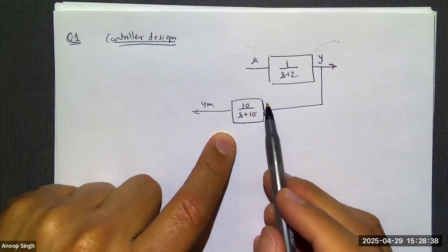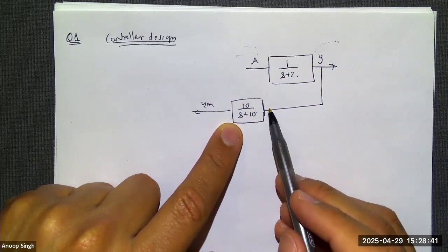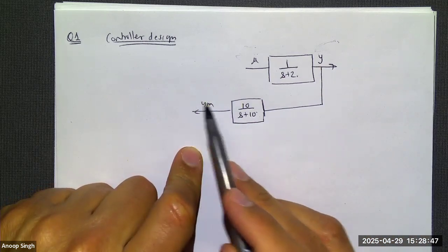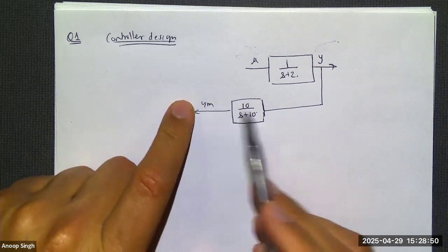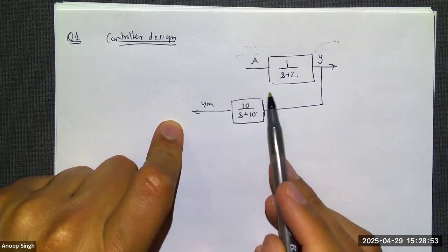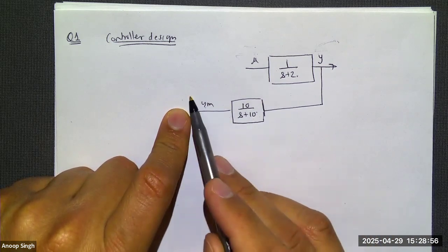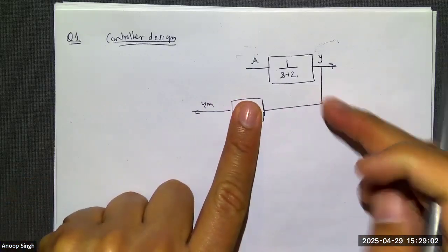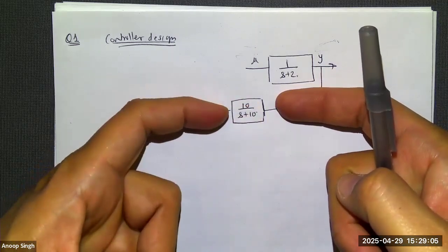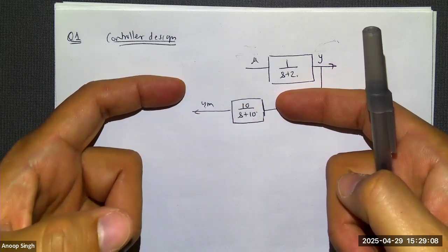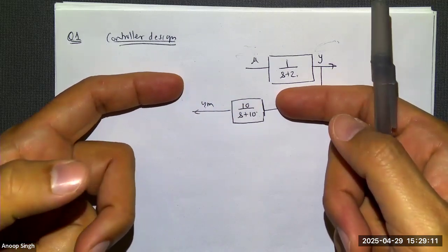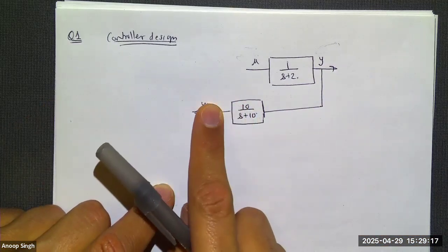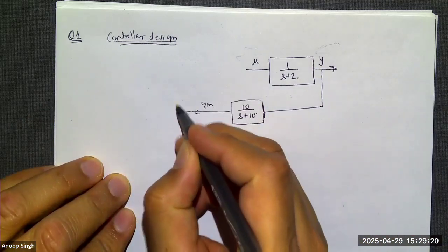Similarly, this is a first order system. If you give some sort of input to it, like the output is a constant, the sensor would slowly give an output, which will start from 0 and build up to it. The DC gain is 1, so it's going to build up to the same value which you're feeding it. And it's going to reach the final value in like 4/10 seconds, so 0.4 seconds. Basically, if you give any kind of input to the sensor, it's going to reach that input in about 0.4-ish seconds. So that's what this sensor is doing. If you give some measurement to it, it's going to build up to that measurement in a little bit.